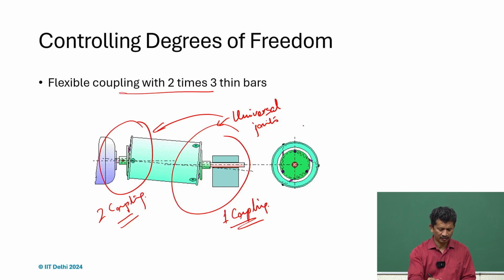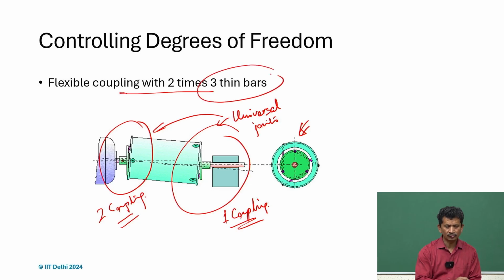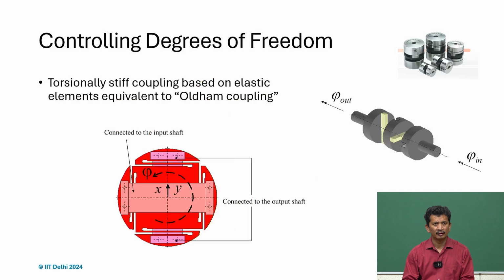So, from the other side, that is what you see. Of course, because of the offset there will be overlapping of the discs, what you see, and even the shaft location will change a little bit. But yes, what is important is that just 2 thin bars we can use, and we can create a very nice mechanism. So, using that concept and one constraint away from the center, now we can have many solutions.